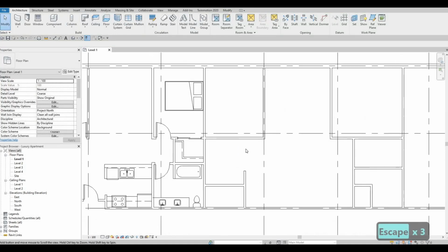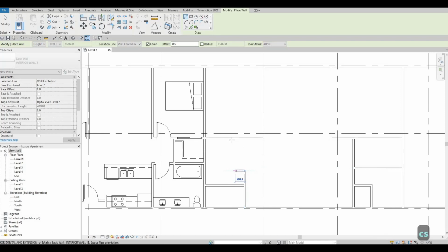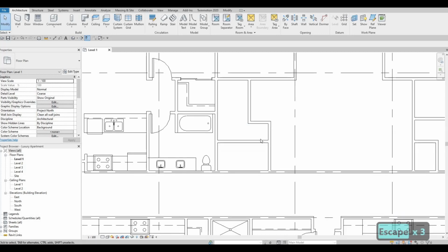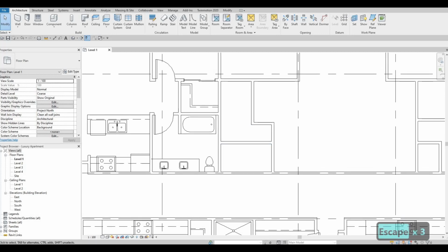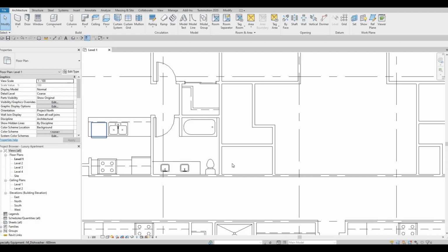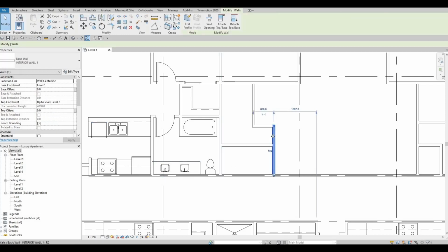Don't you worry, I'm going to give you the dimensions for that. It's easier for me to add the shape first before moving everything else. So here I'm going to select this one. I'm going to reference this wall right here. Okay, so now I'm referencing this wall. I'm going to push this out by selecting this and then typing 2300.